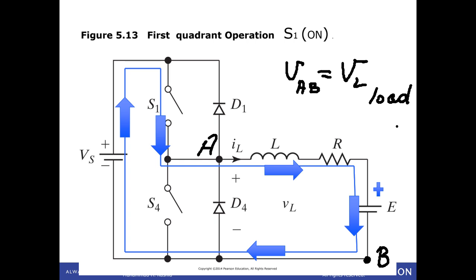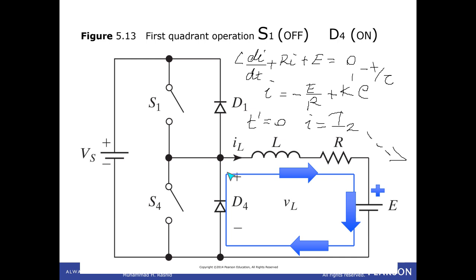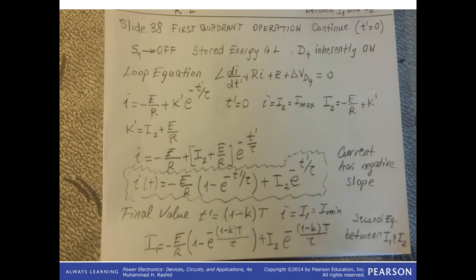Okay? That's step down. That one is step down. First quadrant. That one is the equations of this one. And this one is again first quadrant. So current is rising. Then current is circulating, reducing. Then again rising, on and off, on and off. It's the first quadrant. Okay? And the first quadrant equations, it's not second quadrant. It's still first quadrant. Control switch on and control switch off. This one is off part. And the I1 and I2 could be calculated by this one.